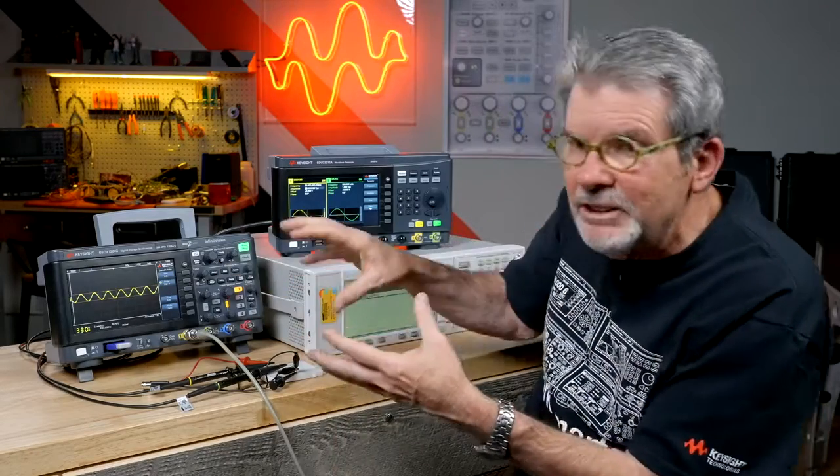So the test I just did to test the bandwidth, that's not the way we actually test bandwidth, manually creeping up and measuring it in the time domain. We actually use what's called a vector network analyzer that generates a frequency response plot like we showed in one of the earlier lessons on Bode plots.